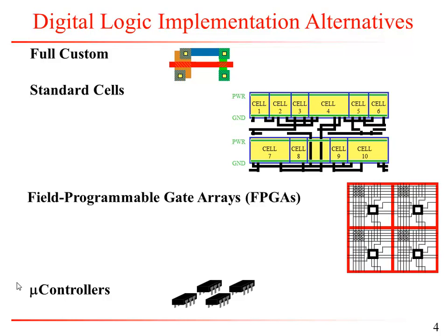in which you manually design, or some other company designs AND gates, NAND gates, XOR gates, adders, and stuff like that. And what you do is you then map your design into these standard cells. And basically, the main advantage of the standard cells is that you can automate the process of floor planning, routing, placement, and so on. And again, you must be familiar with this, with what we did in 5301.